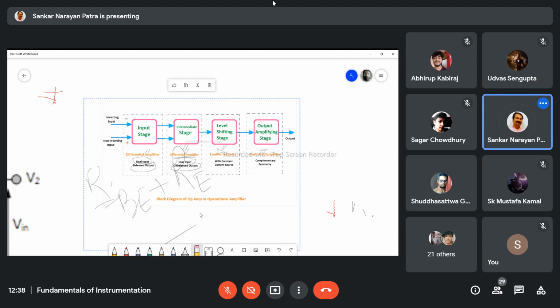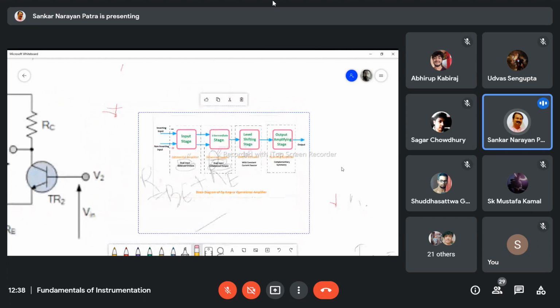Okay, this is the important part. Definitely, it will be discussed in electronic circuit theory. But an electronic circuit is an important part of the transducer for signal conditioning. As you have not understood it earlier, I am going to make it clear in future. Whenever I say signal conditioning part, you just remember there will be transistors or an op-amp which actually amplifies or attenuates the signal as well as filters the signal. These are the important operations or functions of the signal conditioning element or intermediate modifying elements that I started discussing.